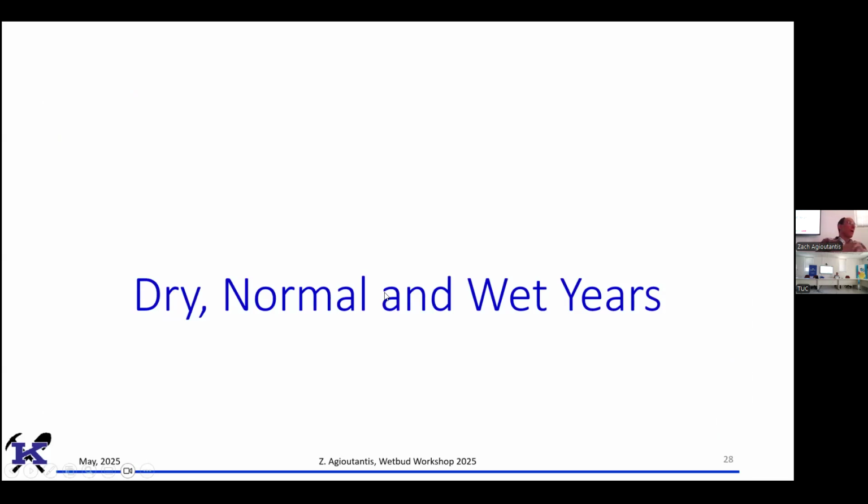Now, I talked about the dry, normal, and wet years. This is important because you need to anticipate very wet years, with high precipitation. You also need to anticipate very dry years. If you do not anticipate your dry years, your wetland is going to die. If you do not anticipate your wet years, your wetland is going to be flooded, and it doesn't function as a wetland anymore. It's a lake.